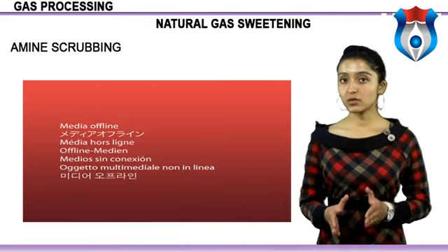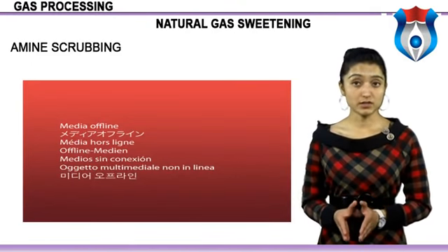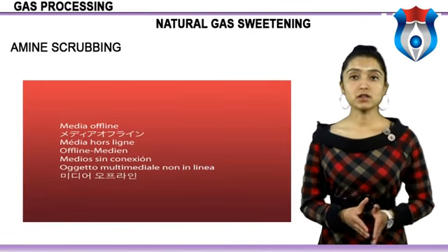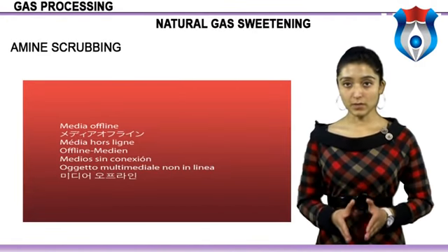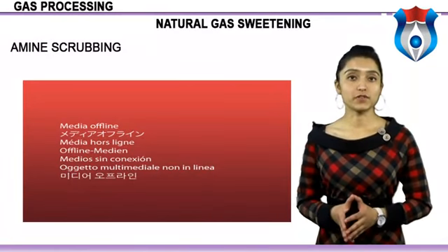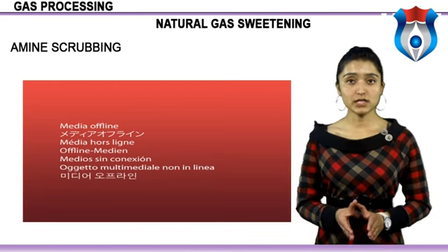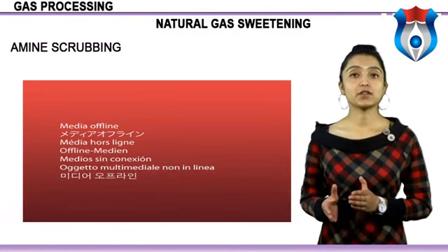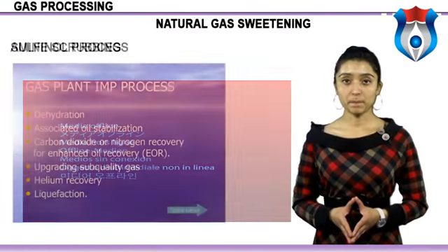The process is also known as acid gas removal and gas sweetening because it results in products which no longer have the sour, foul odors of mercaptans and hydrogen sulfide. A typical amine gas treating process includes an absorber unit and a regenerator unit as well as accessory equipment.